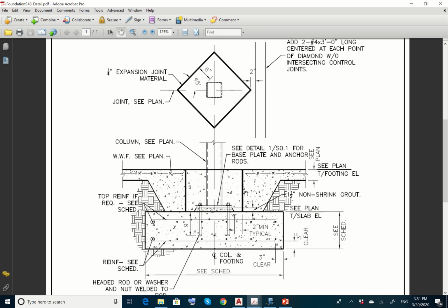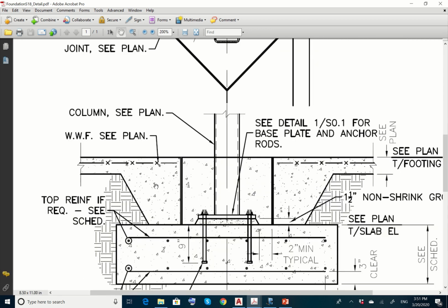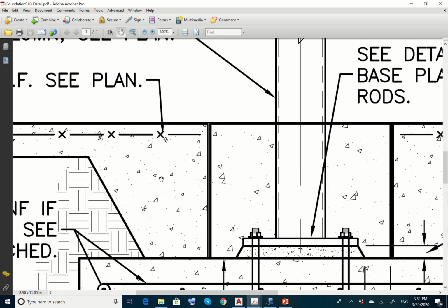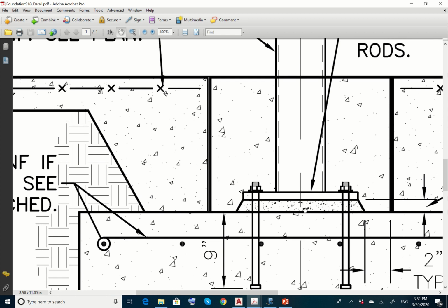As you see, the hatching over here is the indication for concrete. So you have concrete here, there is no concrete here. If you hatch this, you're going to lose points. This is steel going within the concrete floor until it reaches the foundation over here.